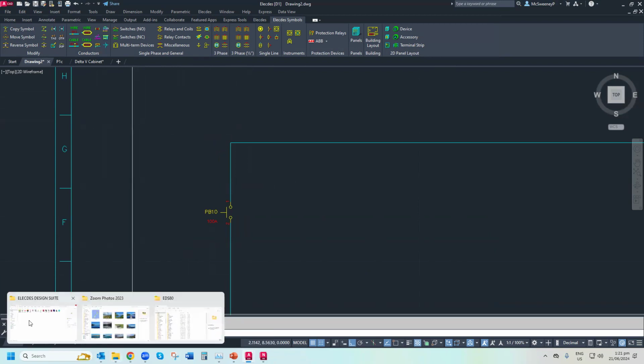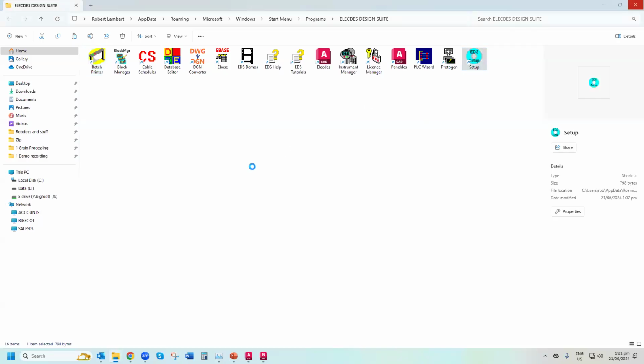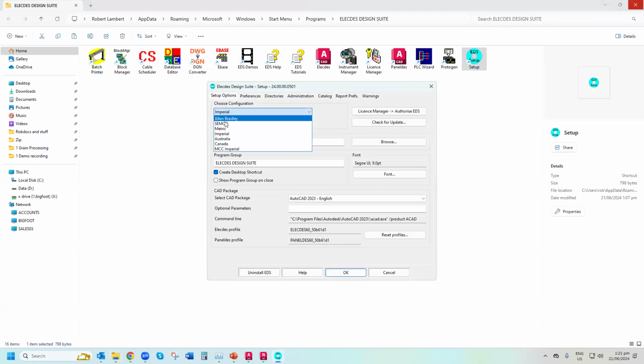Now, again, if I go back to my CAD session, out of the box, we have those 4 examples. Metric, that's the IEC symbols, IEC 617, Imperial. Somewhat ironic, America got rid of the British Empire in 1776. Australia is a slight variation of IEC, although they seem to be reversing back to normal IEC now. And Canada is the American IEEE symbols, but in the metric environment. So there's that. I also point out here that this comes back to flexibility.